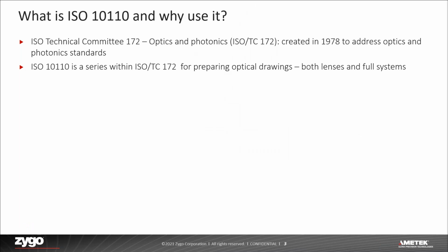The motivation behind this webinar is to introduce people to the ISO 10110 drawing format and explain the coded notation it utilizes. There are many different ISO standards for optics. The technical committee solely responsible for optics is TC 172. The optics drawing standard, ISO 10110, is one series within this technical committee. There are many other standards within this technical committee.